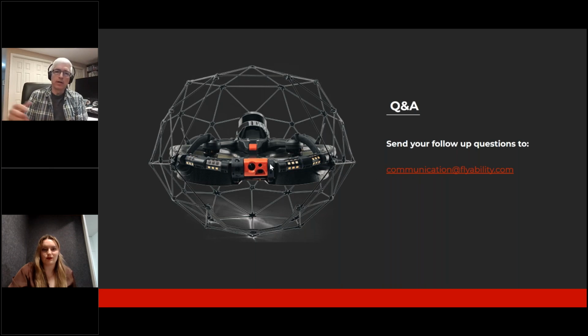as soon as we opened the concrete hatches, the hatch openings are huge concrete blocks that have to be lifted out with a crane. Once we had both of those hatch openings open, we lowered into the vault a range extender antenna, which is something that Flyability provides as an option for the Elios 3. Essentially it is an antenna with some amplification circuitry at the end of a long cable. Since our vault was underground and our pilots were above ground, several meters away from the opening, there was a large amount of earth between us and the drone.